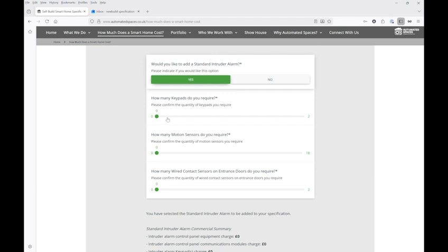Now the slider bar you can grab and pull, or you can click and point. So if we go to here, you can click and it comes up. The thing to bear in mind, as I mentioned, is that because the quantity is 2, the first graduation is in the middle. So if we come back down and put it onto 0 and click here, you can see it's going to pull up to the 1. It's just splitting that. The similar would be true for the 18. If we click in here, you might get it jump up to 2, then you can split that, goes to 1. Or you can hold and drag.